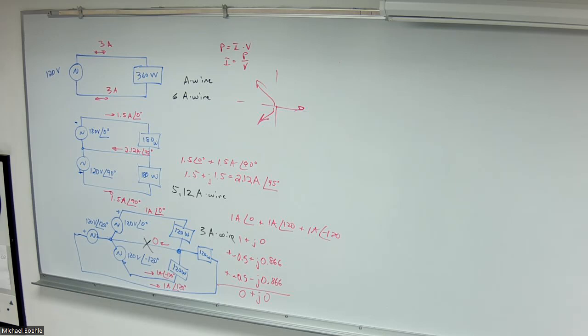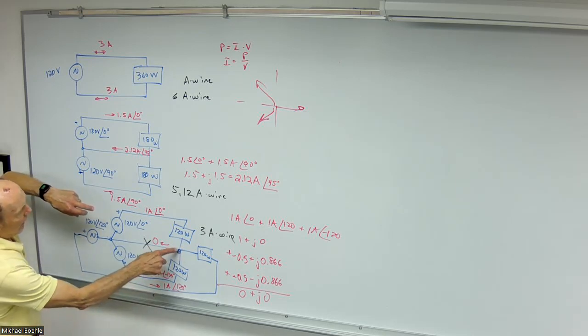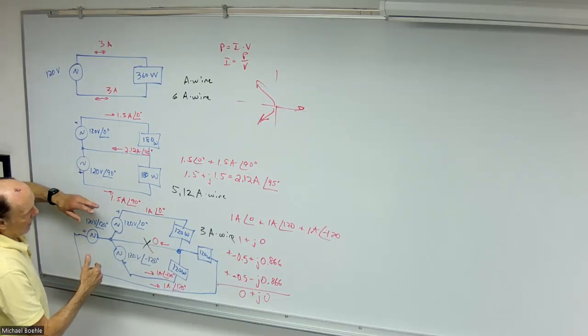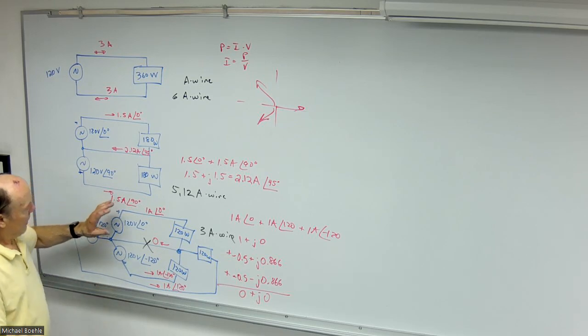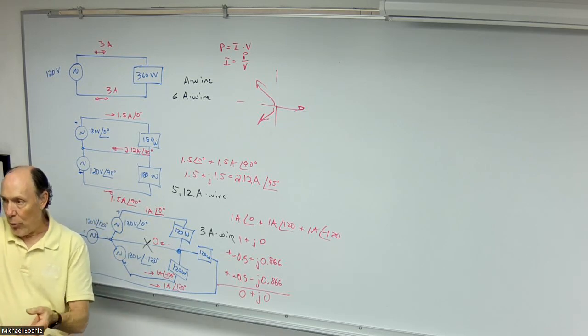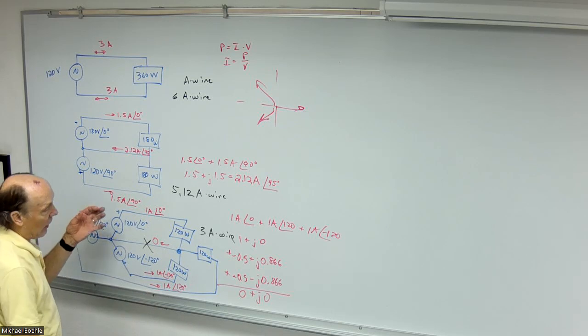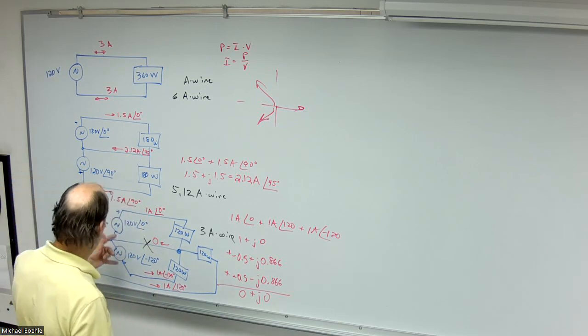Okay. If you ever see voltages like 277 volts for something, where does that come from? Well, I'm using my common connection here, right? But if I actually were to connect from this phase to that phase and measure that voltage, what is that total voltage? Well, I look at the difference.